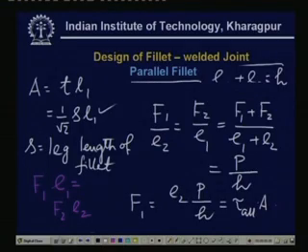I emphasize here, I stress again, that the designs must be such that the welded joints do not experience any bending stress. This is very important, because bending stress is very detrimental for the joint efficiency, or it leads to joint failure. So, this thing must be remembered very well. Now, this was about the parallel fillet joint.